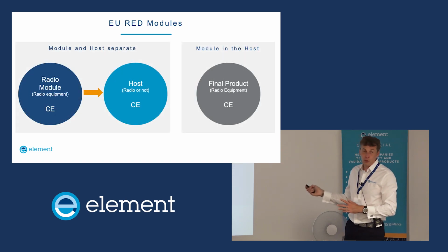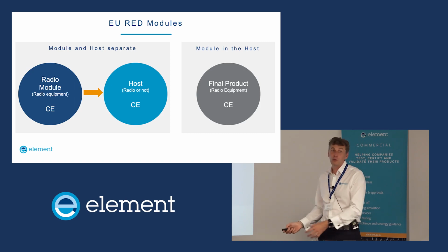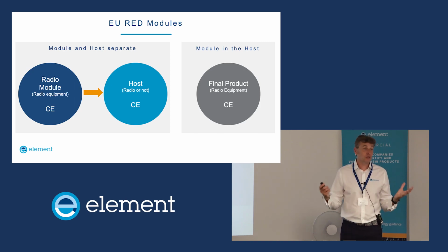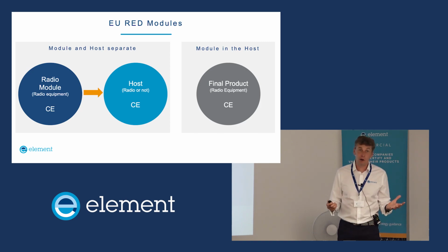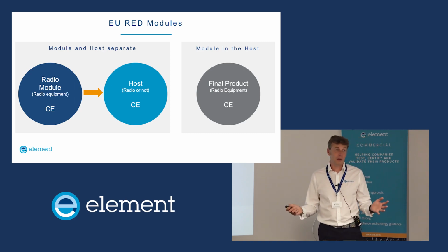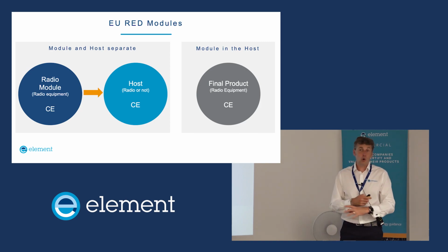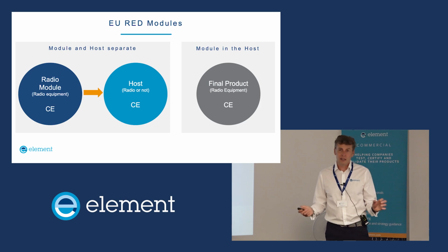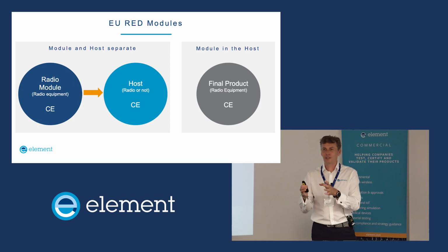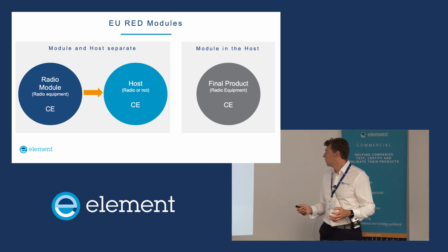So with Europe then, this whole CE marked radio module, there's no modular approvals. You put a module into your product, you're responsible for fully assessing the end product. And you might say, well, actually, safety testing I'm always going to do fully on the end product. That's a given. EMC, emissions and immunity, I'm always going to do fully on the end product. EMC immunity testing of a little module bears no resemblance whatsoever to EMC immunity testing on an end product. So those results don't correlate at all.